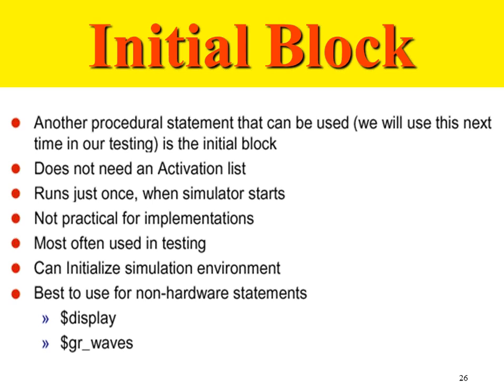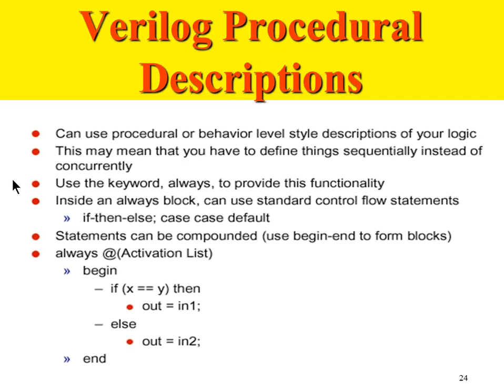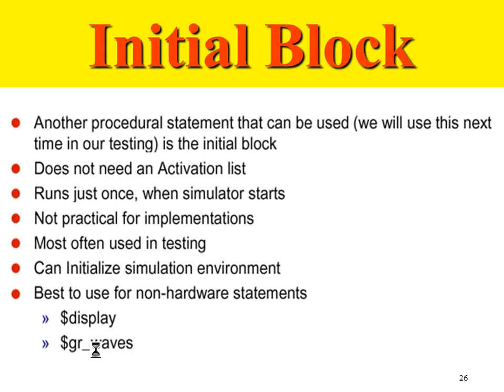And then whatever logic has to continuously execute can be put in an always block. And you can have one or multiple always blocks. The way it works, I think, is there in the next few slides, so I'll not talk about that right now. We'll see how multiple always blocks work. So this is how the initial block and the always block work. Any questions on this?